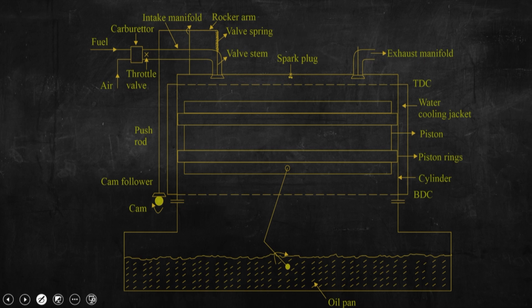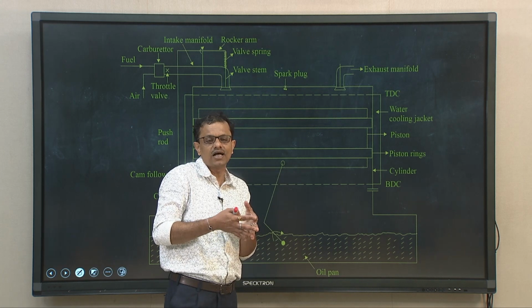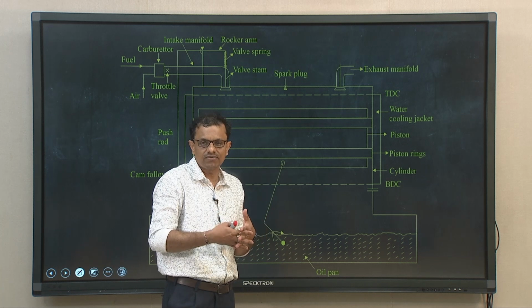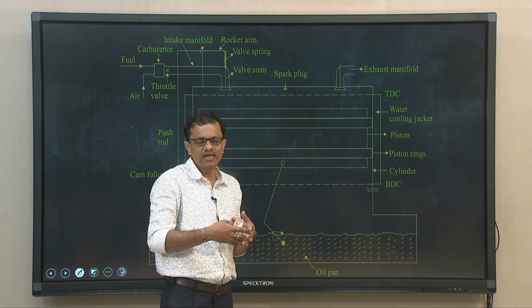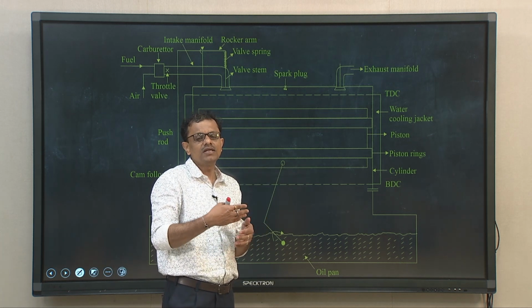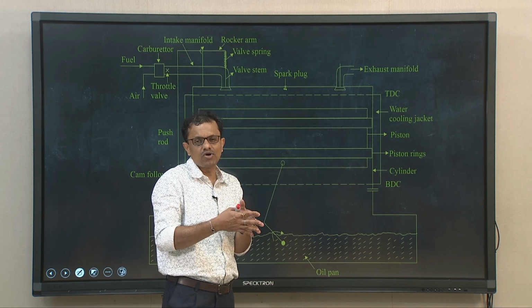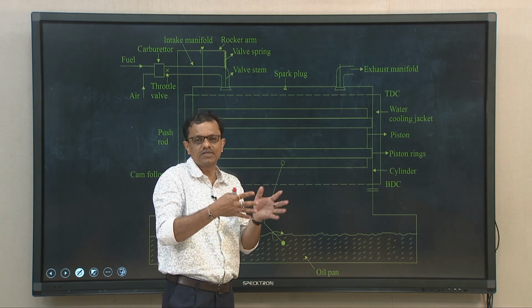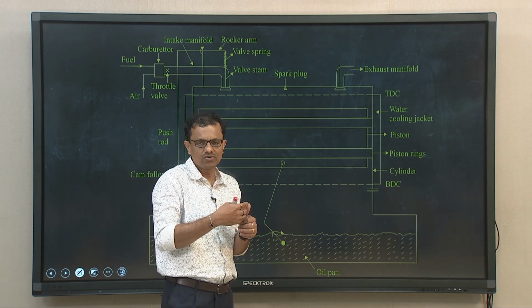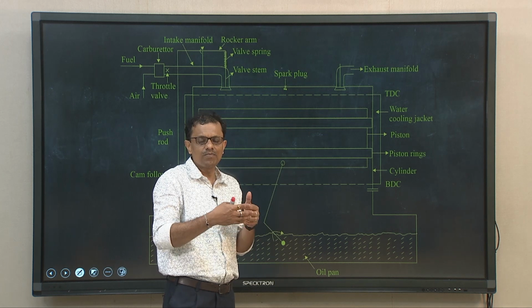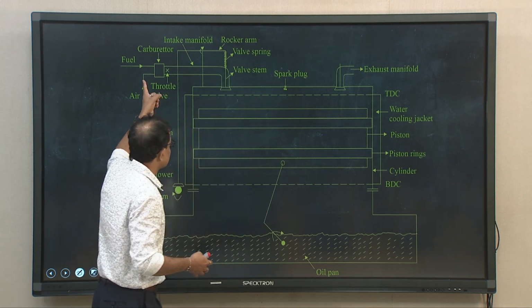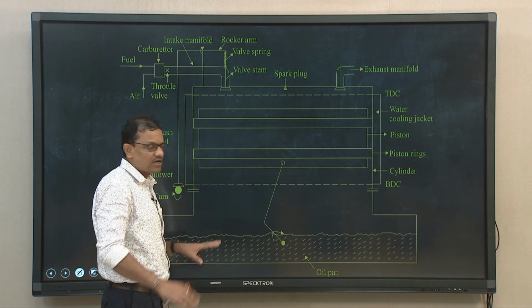As I discussed today, instead of directly discharging all these combustion gases into the ambience, we can take that high pressure, high temperature gas to rotate a small turbine, and you can also connect a small compressor to the common shaft of the turbine, so that we can run a compressor. The compressor can compress the intake air. So, this is called turbocharged.